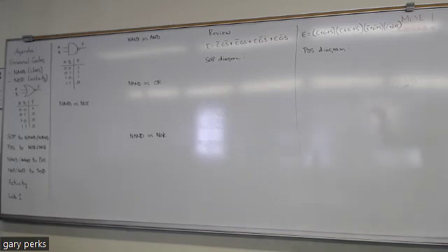And those are the two equations that you would use in an assign statement in your Verilog design file. Remember, lab 0 just had the one assign statement because you just had one equation. But for lab 1, you're going to have two assign statements because we have two equations. So you might want to call one output, like F_SOP, and the other output like F_POS.